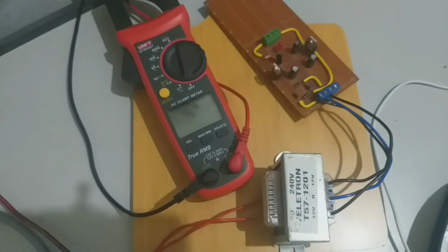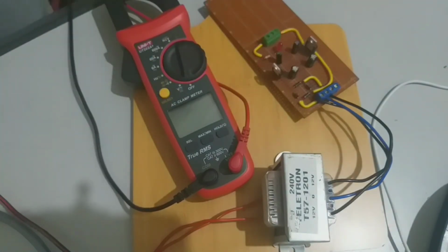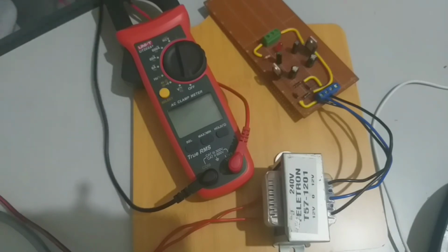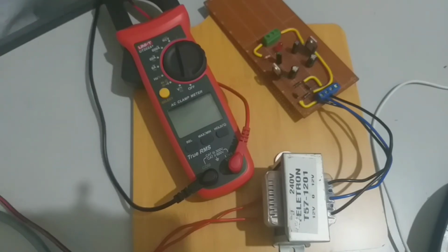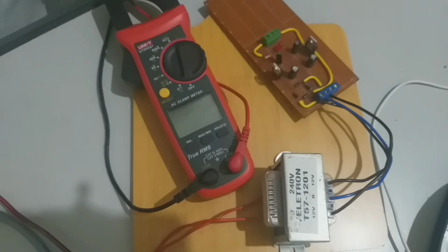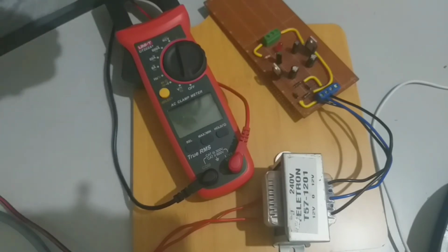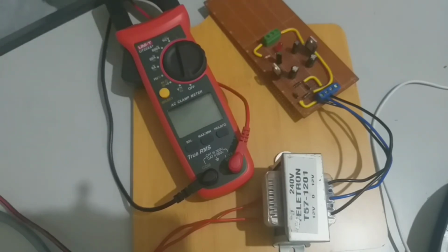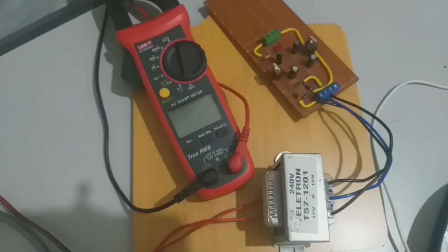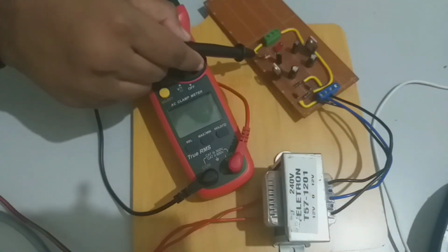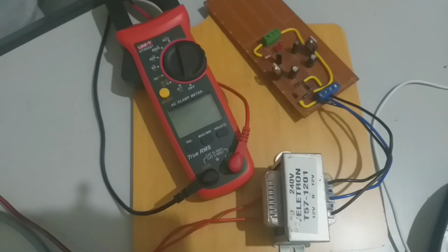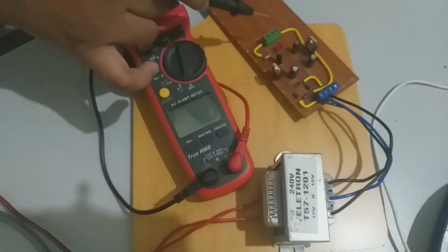Next, the process involved in the circuit is indication. For the indication process, we include a 5 mm LED. If there's a current flow, the LED will light up. Here, we can indicate whether the current is flowing or not. At the same node, we used a 68 ohm resistor for the LED to light up, which is here, the resistor and the LED.